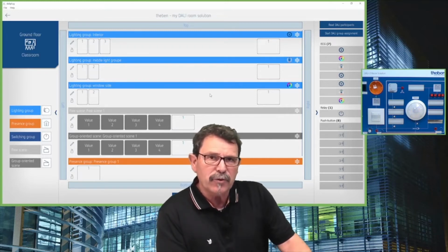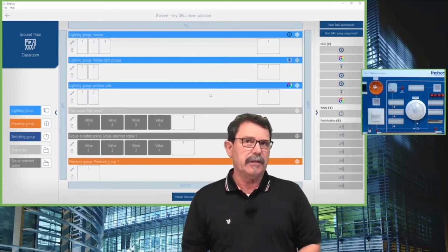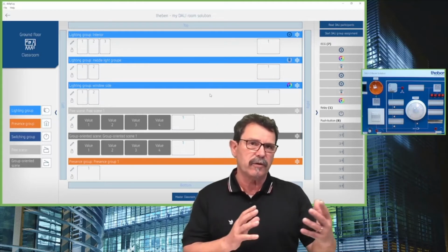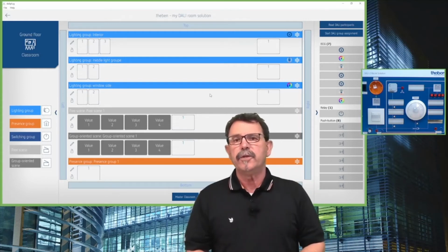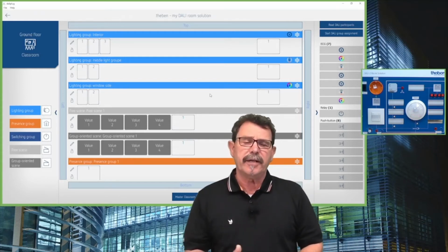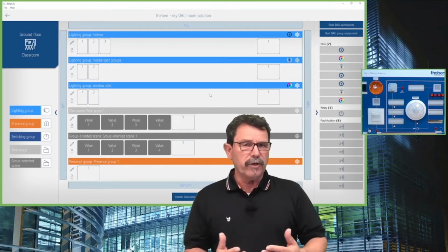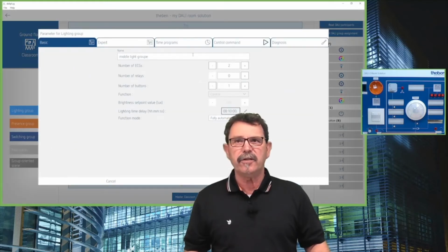First of all, I have to inform or to update you. If you intend, as an example, to control tunable white with a static curve, so according to requirements for offices or for schools or for hospitals, however, so an automatic curve, which we do have in our software, and I will make you acquainted with it, we call up just a template, so then there's no need to modify the color temperature. But if you intend to do so, then we need a second option, a second push button finally, and this we have to do here.